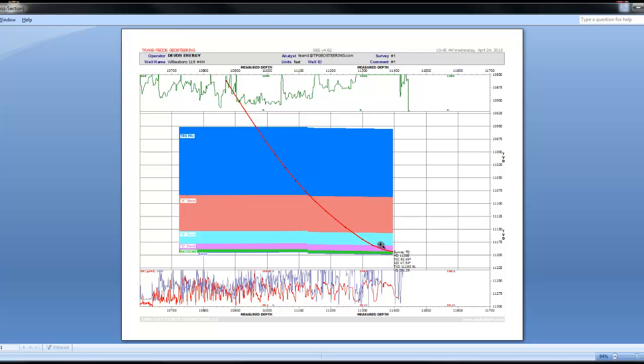Right now it's kind of zoomed out, but we'll be able to actually zoom in at a later time. All of our LWD data that we wish to display can be shown. Up here we have the gas and we have the gamma ray and the ROP displayed down here, which is what we normally get a chance to produce.